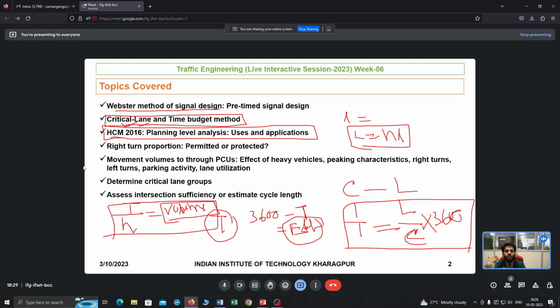So now once you know that this movement, the right turning movement, is protected or permitted, and also normalize or adjust your volumes based on the actual existing field scenario, which is obviously different than your base scenario, then you can calculate what the critical lane groups are, right?